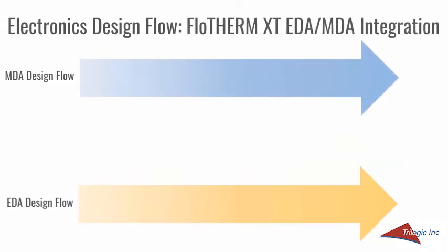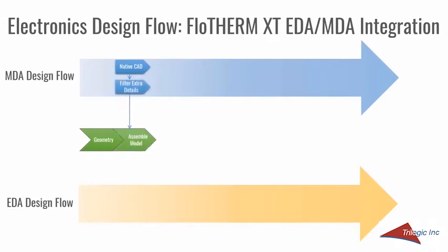Let's now look at the thermal design process with FloTHERM XT. The create geometry step is as before. However, the geometry can be CAD geometry, created within FloTHERM XT or smart part based. The assemble model step is compressed because FloTHERM XT can directly work with CAD geometry, so CAD can be exported in the CAD system's own native format and used directly in FloTHERM XT. If required, unnecessary detail can be removed by rewinding features of the model within the CAD system.